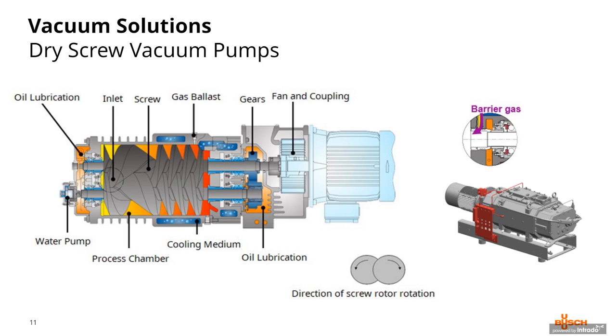The dry screw has several seal options: labyrinth or mechanical seal, selected by the application engineers when analyzing your process gas chemical composition. In addition, a seal purge gas flow option can be added to help protect the mechanical seals and gearbox from contamination. The seal barrier purge is basically the injection of nitrogen gas into the seal, and by creating overpressure here, you keep the process gas out of the gearbox. So the main advantage here is protecting your gears, the bearings, and preventing any type of oil contamination.